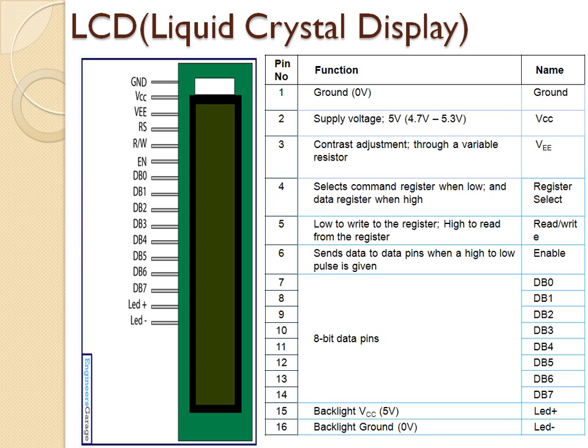Okay, so after placing the data onto these data pins, we'll place the data onto these data pins. Then there should be a transition from logic high to logic low on this particular pin, so that this information will be latched onto the LCD.